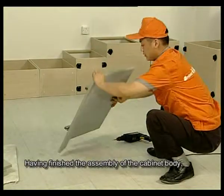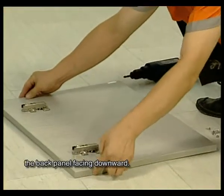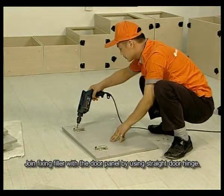Having finished the assembly of the cabinet body, lay the cabinet body on the floor with the back panel facing downwards. Join fixing filler with the door panel by using straight door hinge.